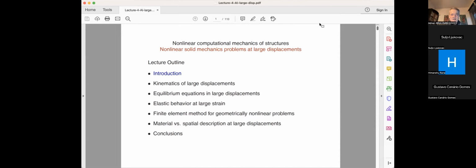Today we enter what is described in chapter 4, and this is a question of large displacement and large deformation. If you study now the geometrically nonlinear problem, the key point is that the displacement and deformation are so large that you can no longer pretend that there's no difference between initial and deformed configuration when it comes to computing either derivatives or integrals. Integrating over the deformed configuration, which is significantly different from the initial configuration, you will not get the right result.